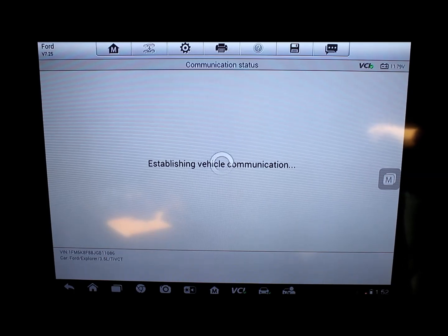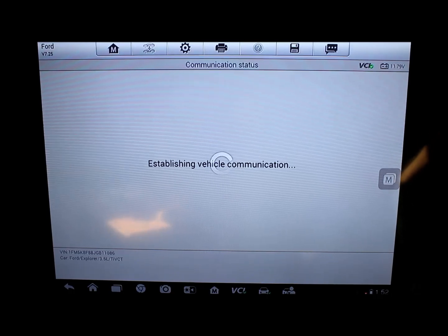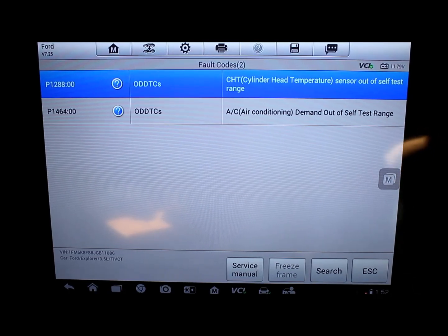You'd hear the AC compressor clutch click, vent solenoids, purge solenoids. So it's checking what it can statically, basically electrical problems. It can't check something like fuel control because obviously with the engine not running, we have no fuel control.